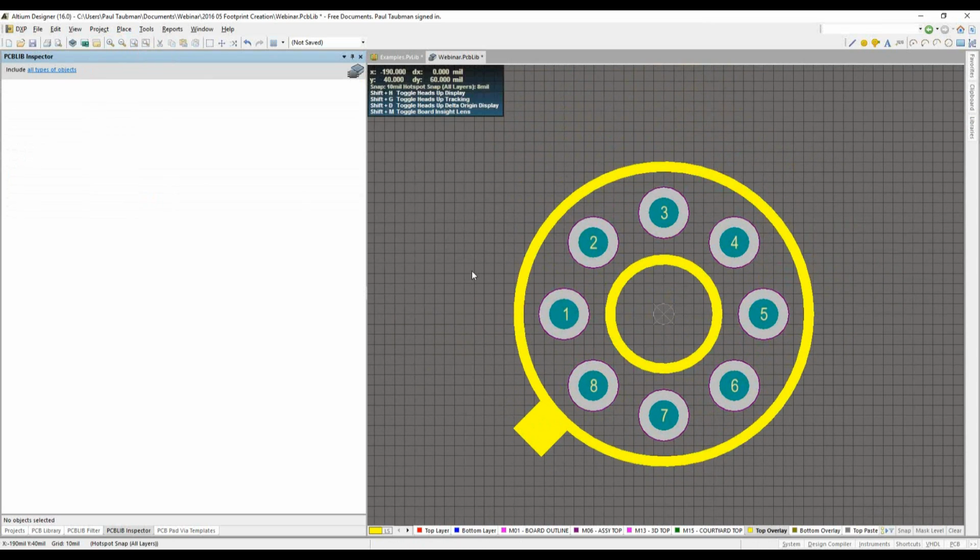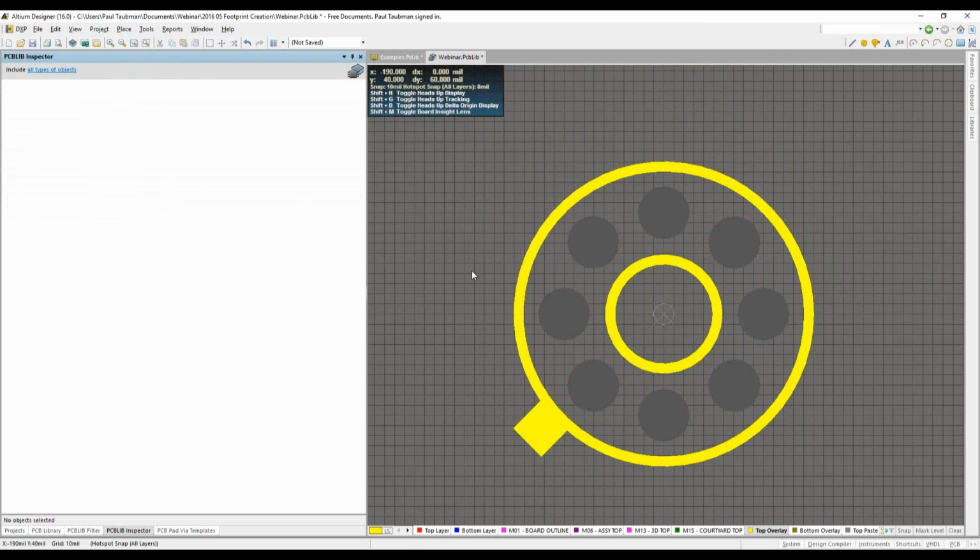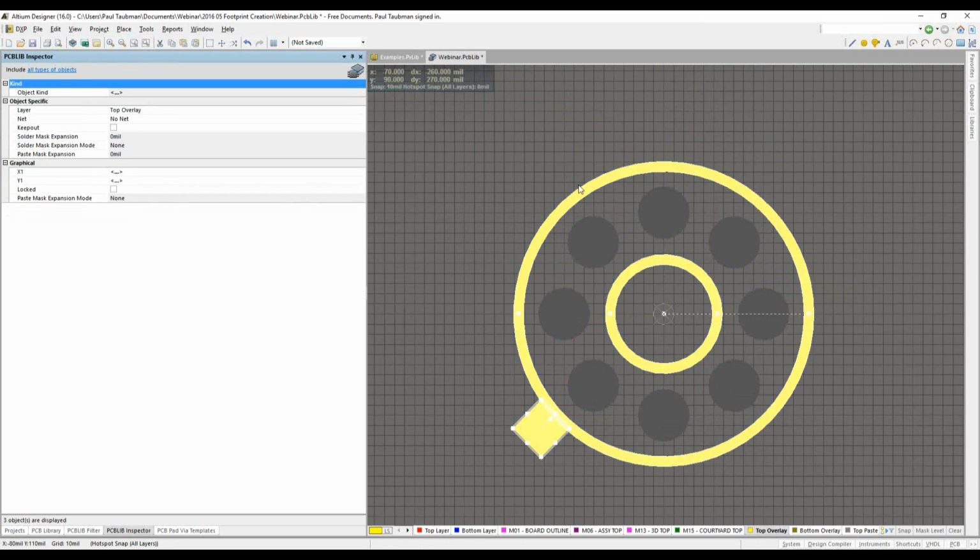And the way I can do this very easily is there's a key called Shift S, and that puts me into single layer mode. By doing single layer mode, it's easy to select things that are just on that layer alone. So again, I'm going to select sweep over, so it's just doing a left mouse click, sweeping over everything, making sure it's fully enclosed within the box. And I'm just going to do another Control C.